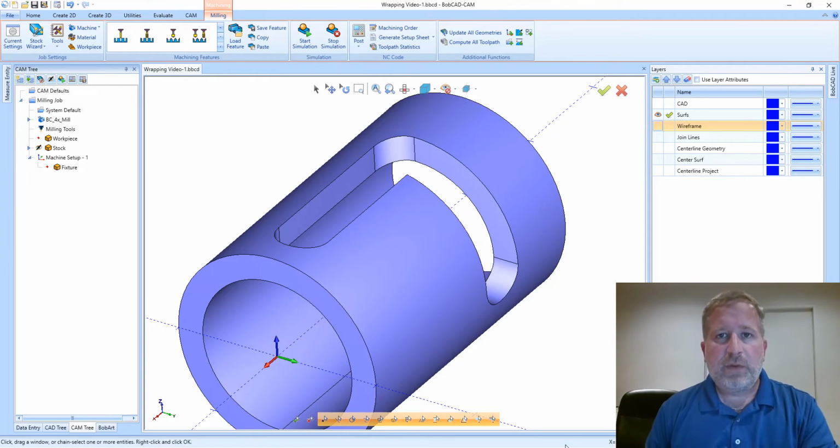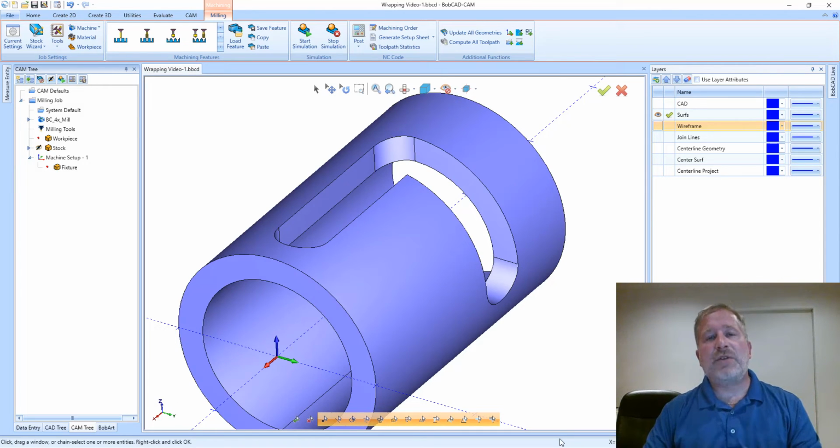So in this video, what I want to take a look at is using a wrapping group and some of the common problems that we see people contact in to support and have questions on because they're kind of confused in how the wrapping group actually functions. So what I want to do is try to solve some of those confusions and help you guys to understand how the wrapping group works so that you can know when to use this path and what it's good for when cutting slots on a 4th axis rotary.